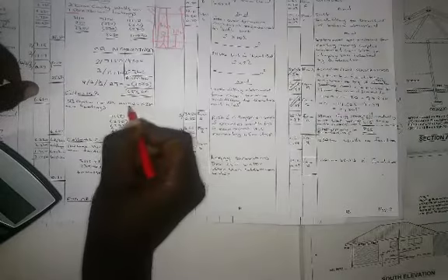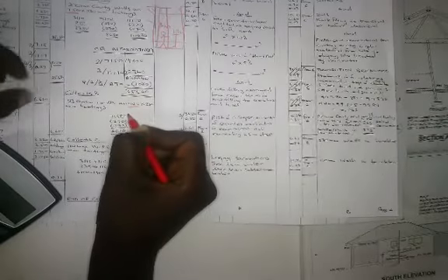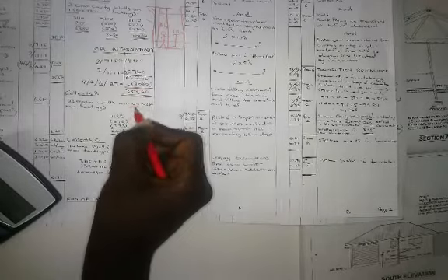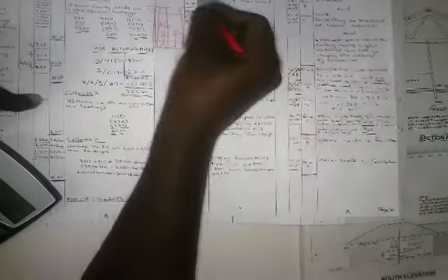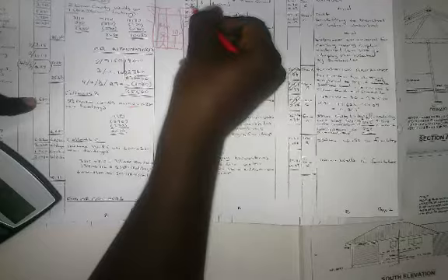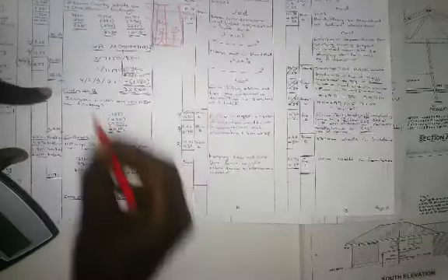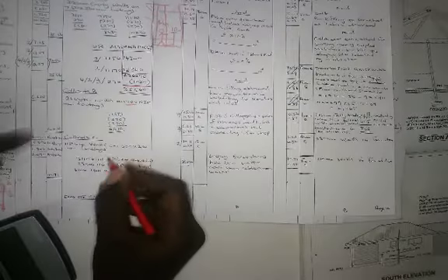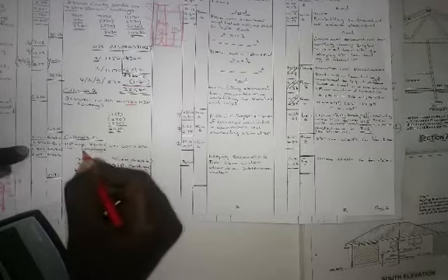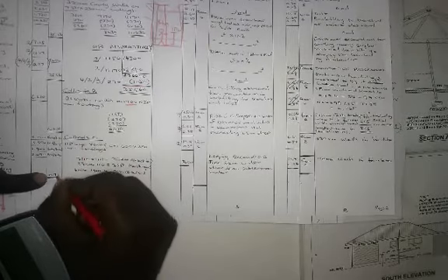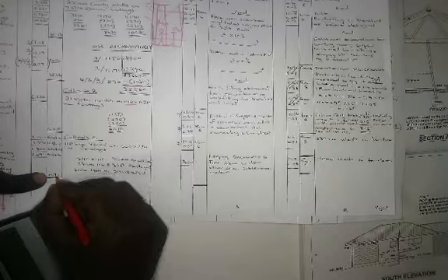And then you come to B for your 230 wall. Same thing. You take your center line over there, and here we've been told that our width is 0.7. There you are: 6.6 times 0.7 times 0.8, that is your depth.